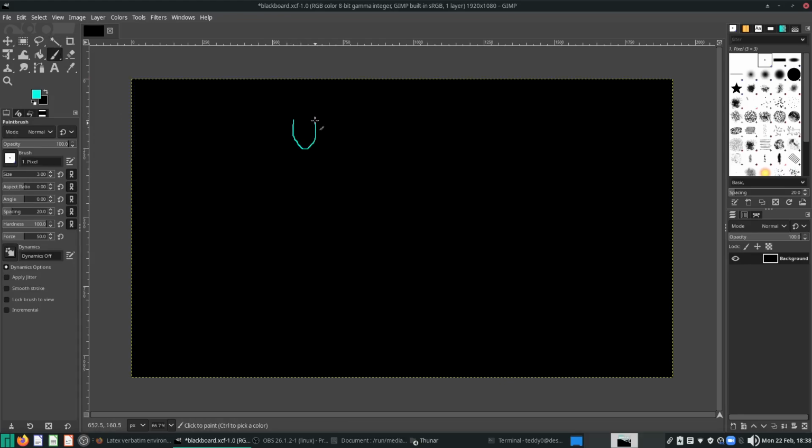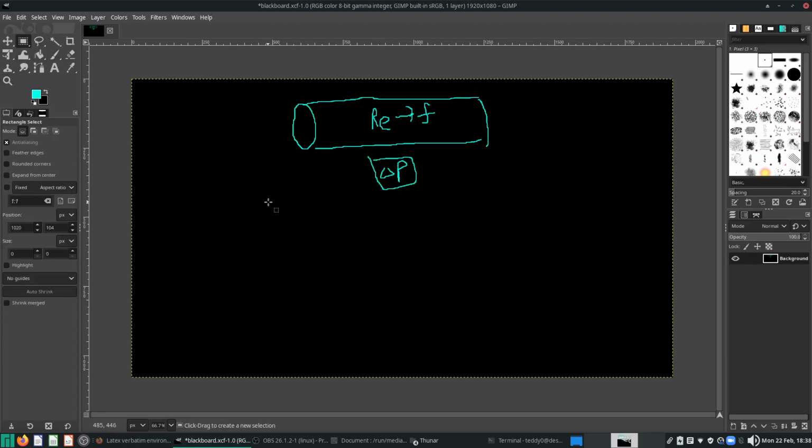In fluid mechanics, what we are very concerned about, at least from an engineering and heat transfer perspective, is the pressure drop. Normally, when you have a steady flow of fluid through a pipe, you have the Reynolds number, which helps you determine a friction factor, for which you can develop a loss coefficient.